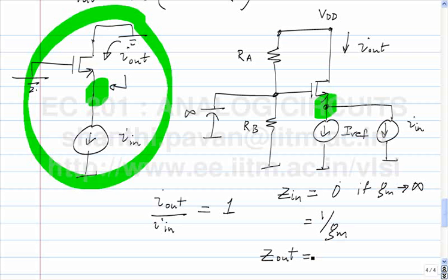Okay, you don't know, how will you find out? You draw the incremental equivalent circuit. For the transistor, the incremental equivalent circuit at this part here is simply a current source. Since that's a current source, obviously the impedance looking in here has got to be infinite.